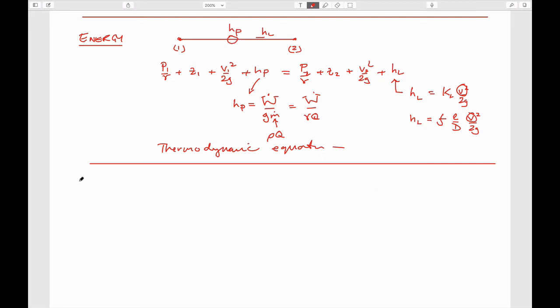The second component is dimensional analysis. And the basic idea here is that if you can group the controlling parameters of a system into dimensionless groups, then you can examine the behavior of those groups individually and reduce the number of experiments you'd have to do and draw correlations between behaviors between a model and a prototype.